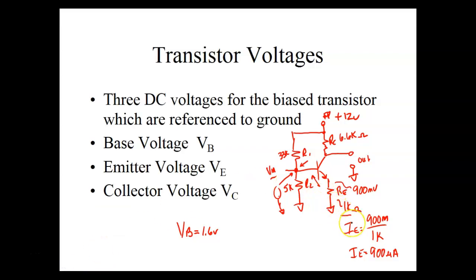What we're doing is taking Ohm's law and applying it to a circuit that we can get a gain out of. This is not a passive circuit, this is an active circuit. So here comes IE right here. Where does it go? Well, about 1% goes that way, so we're going to ignore it. We're going to look at this guy right here.